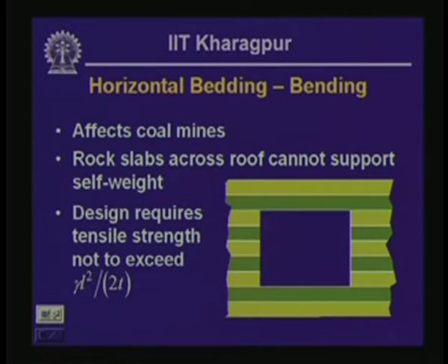So basically what is preferred in this particular case, and that is often adopted in design, is a square cross section of the tunnel, because if you have got a square cross section, then the slab near the tunnel crown, the roof of the tunnel, is not likely to lose any thickness, and as a result the stability is going to be much more.